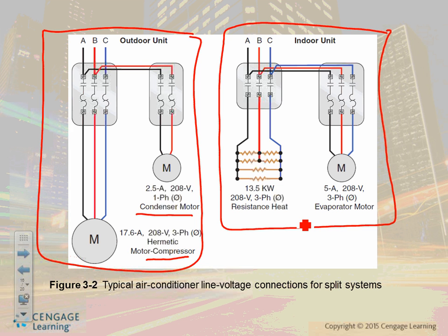How do you collect the heat? You come here, the indoor unit. The indoor unit, guys, they call it the evaporator. So this guy pulls the air through the evaporator coils, the indoor coils, and the coils collect the heat, send the heat to the compressor, and with this condenser fan, throw it all the way outside, and they keep doing it over and over again. Anybody can tell me what this is doing for a living? That's your heat, because it's a heat cool system. So if you're not cooling, then you're heating.